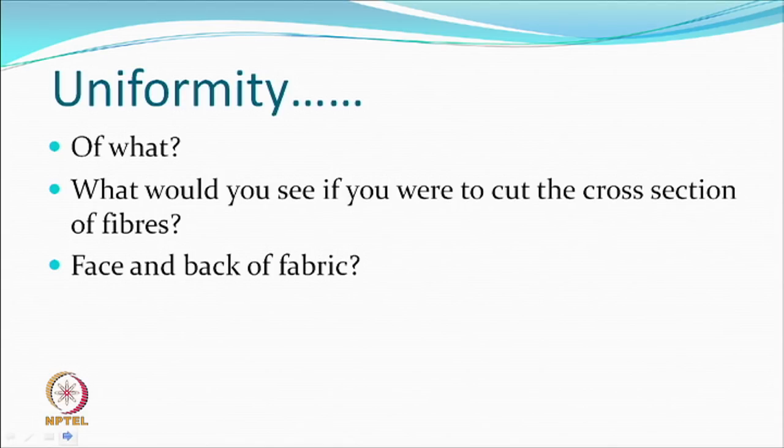It is what you see, but what you see from the same recipe could become different if you change the time of steaming, and suddenly you find, oh, everything was same, shade is not matching because something else changed. Equilibrium is not reached. Equilibrium can be reached only if the same print is seen on the other side. The face and the back of fabric.